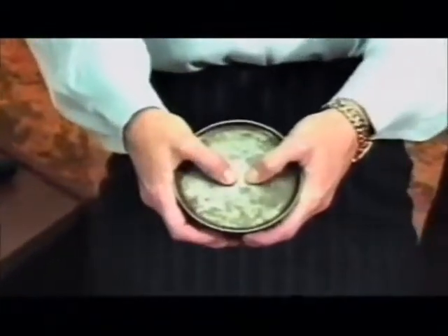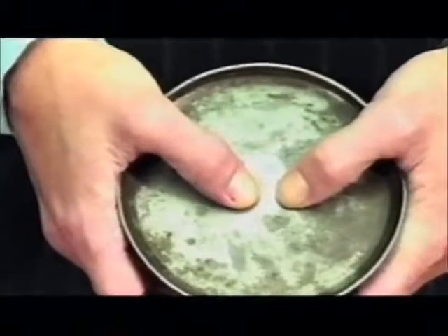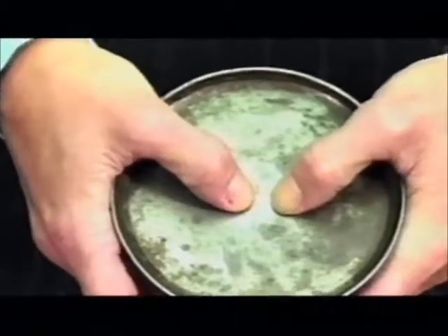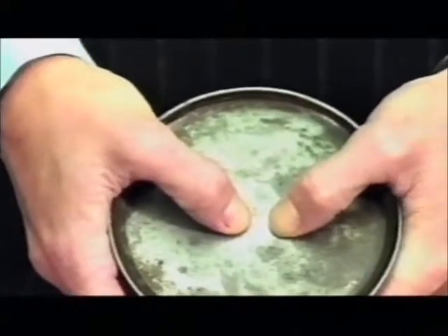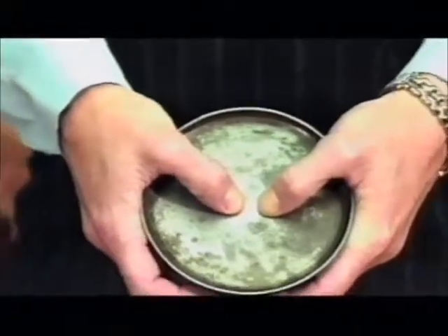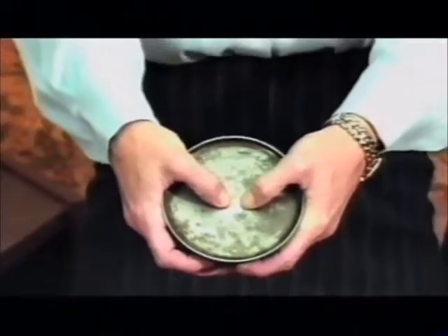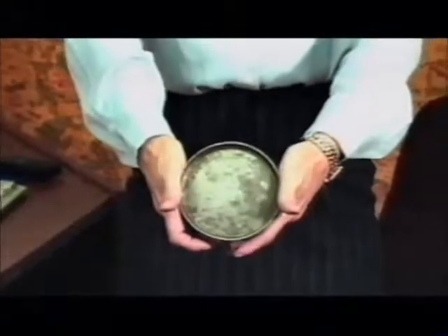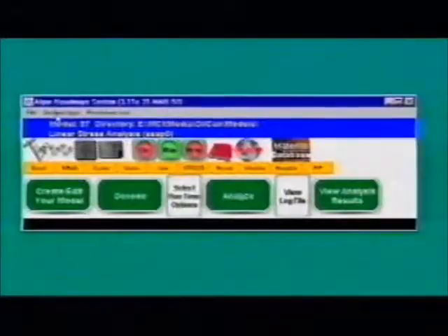Note, as I press on the bottom of the can, the movement seems linear at first. But as I press harder, there's a sudden snap, and a relatively large displacement occurs in a sudden jump. Then, when I release the pressure, it suddenly snaps back. To determine the thickness of the bottom, we purchased 2 identical oil cans and cut out the bottom of one. We measured the thickness at 10/1000ths of an inch, or approximately 1/4 of a millimeter.